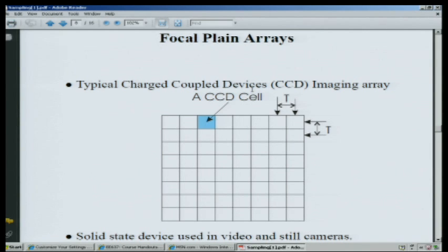Those things tend to be kind of nasty. They were heavy and they saturated pretty easily. They had a lot of various kinds of problems. I mean, it turns out tube technology is still preferable in some applications where you want to count photons at very low light levels. But Vidicon tubes have pretty much gone to the wayside, and they were replaced by CCDs, which are called charge-coupled devices. Now, CCDs are still analog devices, but they're analog devices on silicon.